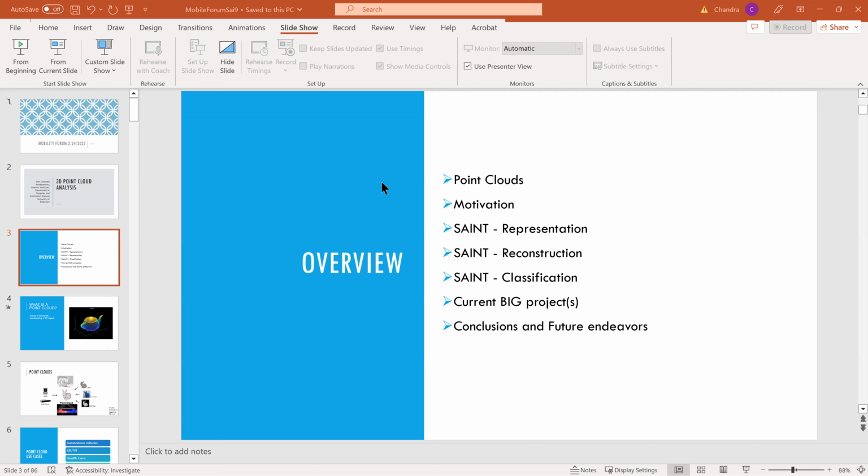So let's take the depth map. A depth map basically is 2.5D. So you take, let's say, a depth sensor, Kinect, for example. It projects invisible IR structured light onto the object. And there is another camera that uses that structure. And from that angle, it records 3D. But then it's giving you 2.5D, really. It's not giving you the complete 360 degrees, right? So depth maps are usually frontal parallel 2.5D.